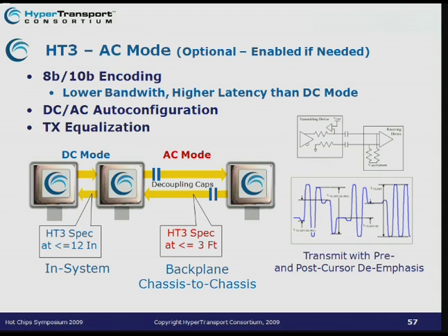How do we do that? Well, in this case, we can no longer keep using parallel links, and we have to switch back to technologies used by other interconnects like 8B/10B encoding with embedded clocks, so that we need some clock recovery circuitry, and therefore we increase the overhead and things like that. But it's a good idea if we want to reach longer distances. Obviously, this is self-configured at boot time.